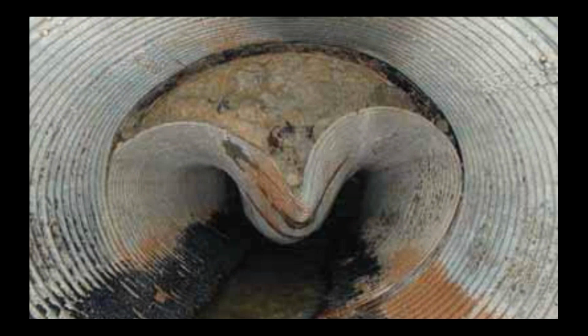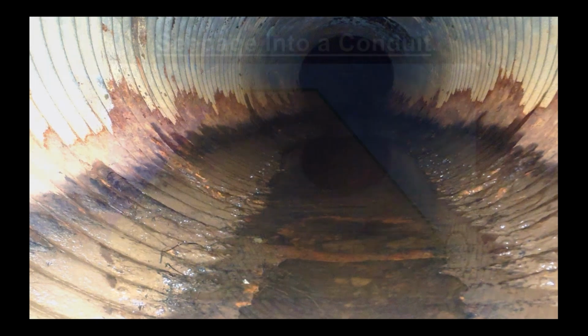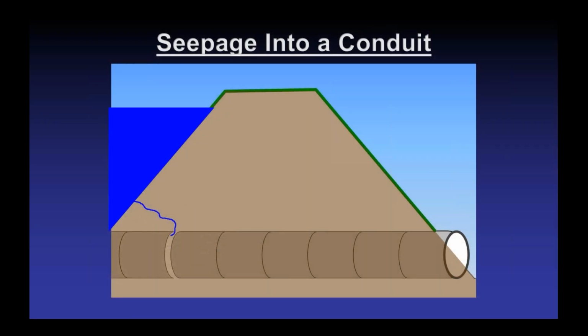With some conduits like corrugated metal, they can deteriorate with time, and you can see this one here clearly failing, because either it's just losing its strength over time, or it wasn't designed for this loading condition with this much embankment material above it. But most likely what you will have, especially with the corrugated metal pipes, is that they can deteriorate and corrode over time.